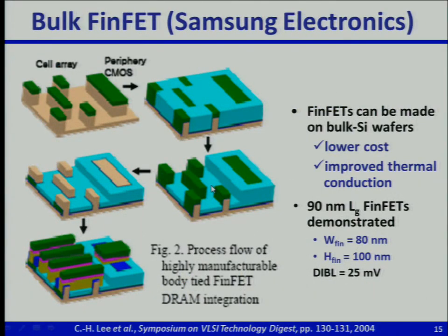So that's, in principle, the only extra step you need to form a FinFET. So now you've exposed the sidewalls, and then when you form the gate oxide and the gate electrode, the gate electrode will naturally straddle the narrow, tall fins, and it'll naturally be flat, planar across the unrecessed areas. Okay, so in principle, you can make planar bulk MOSFETs side by side with a bulk FinFET.